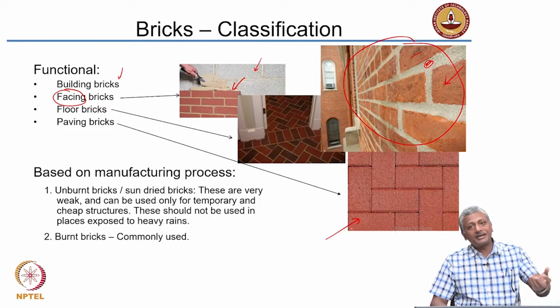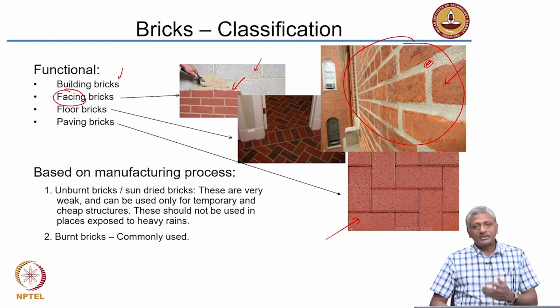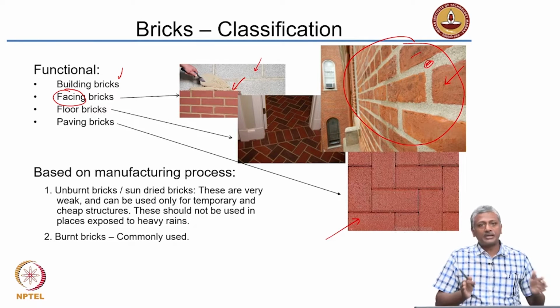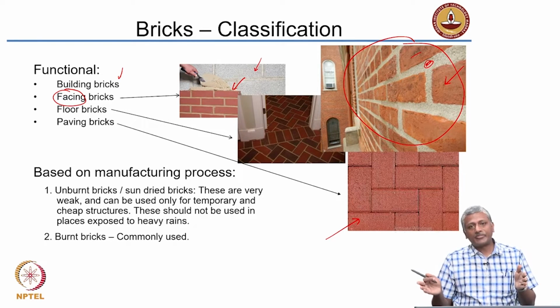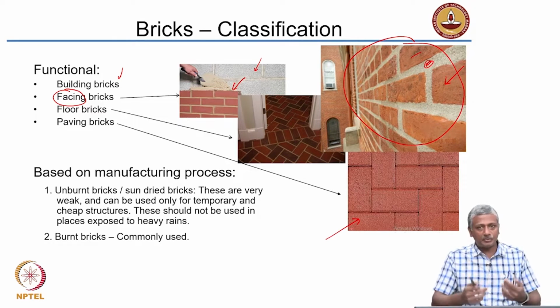Sometimes even in parking areas, in academic institutions, especially when you have cycle parking for instance, you often see the use of flooring bricks. What is the difference between a flooring brick and a building brick? See, in a building brick, typically it has to ensure that you have a good environment inside the house and protects you from the weather essentially. So, a building brick should not absorb too much moisture and should protect you from the effects of the weather. I will touch upon that a little bit later.